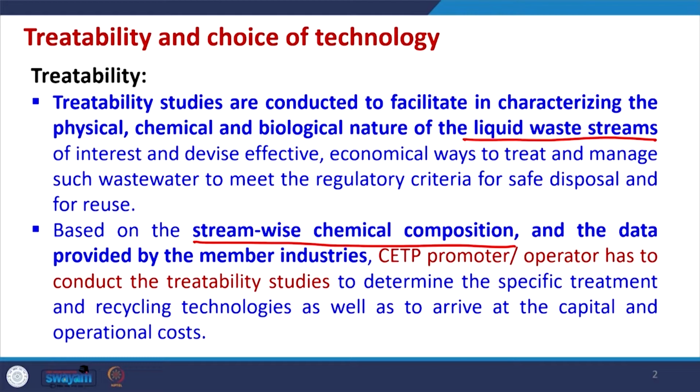Depending upon the data provided by the member industries, the CETP promoter or operator has to conduct treatability studies beforehand at laboratory scale, plant scale or pilot scale to determine the specific treatment and recycling technologies to be adopted in the CETP, minimizing both capital and operational costs.